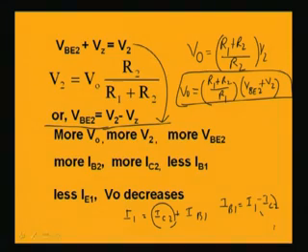Now look into this expression for this output voltage: for a particular voltage regulator circuit, R1 and R2 are constant, they are not going to vary. Then VZ, a Zener diode, after breakdown, that voltage is also constant. VBE2 will be almost constant at that particular transistor base emitter voltage. So the output voltage V0 is basically constant, that can be seen from this expression itself.